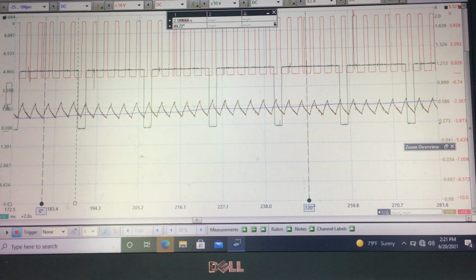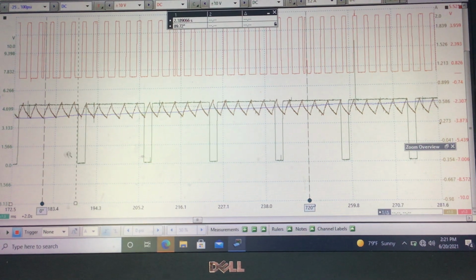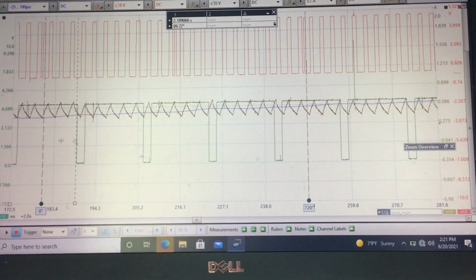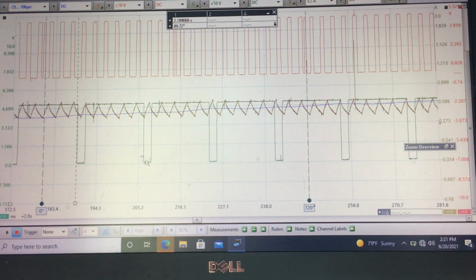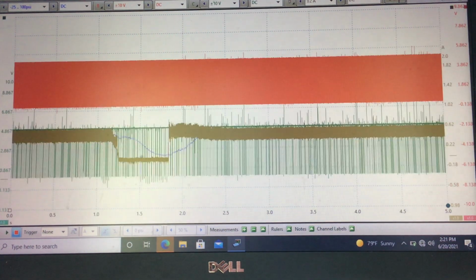This green action on that cam sensor happened earlier, happened to the left of our capture. So that's sooner. We always think of the horizontal plane on the scope as a clock, and this is earlier and this is later to the right. So anyway, let's keep going down the line and analyze it some more.